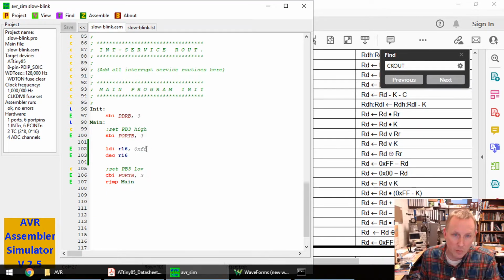Okay. We can get one more out of this by messing with the unsigned overflow. I'm not going to do that right now. Minimize the confusion. Here we go. What do we want to do? RJMP. And we need a label. Do that. Call this loop. I'm using uppercase letters for my labels.